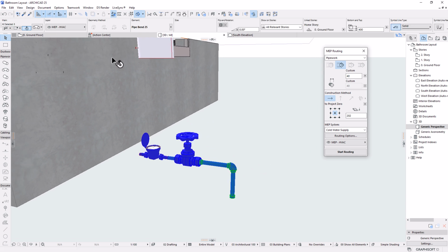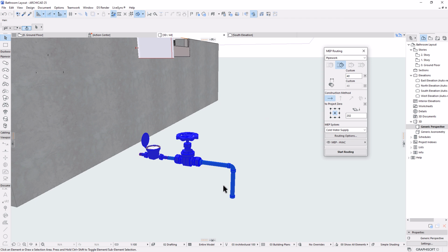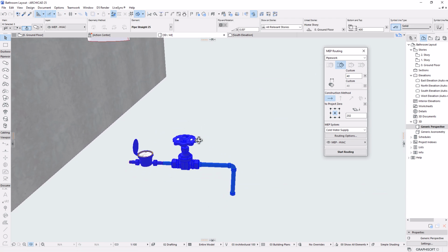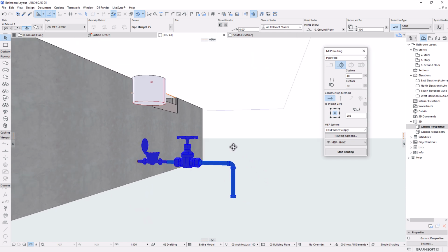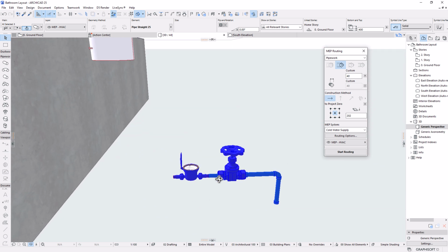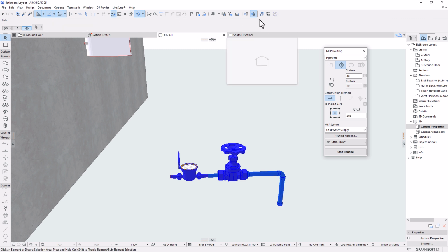Right, I'm going to change also for the bend. Let's go to connections, set the diameter to be 25. All right, now you have a clean, nice stop valve and then the meter from the main connection. So it looks great. Now I could see, like I was saying, if you use this tool to check all the connected elements, that's how you can analyze your, okay, let me do it again.